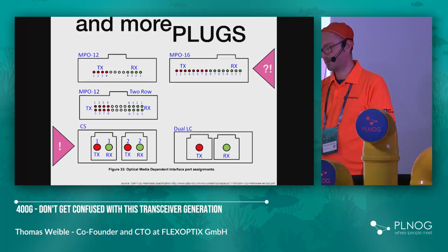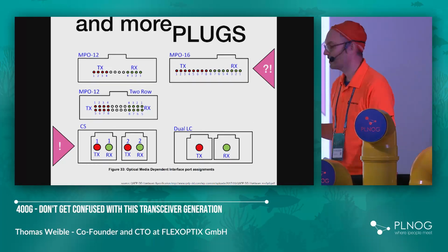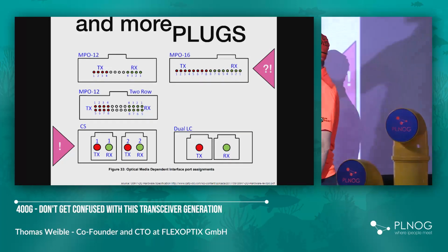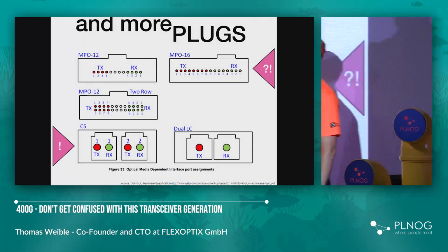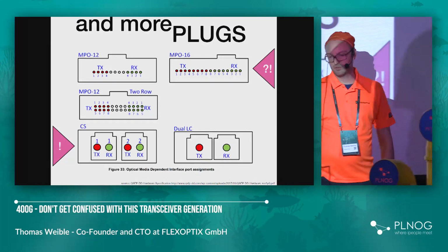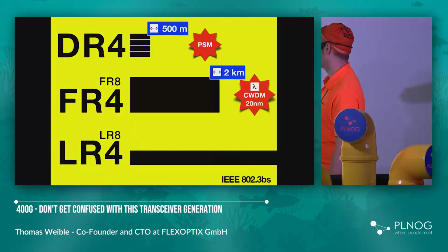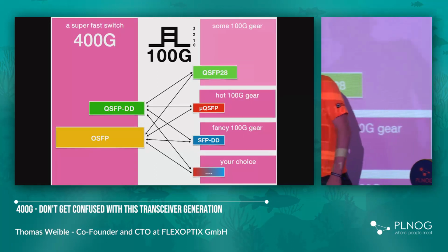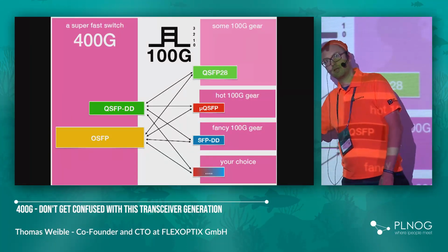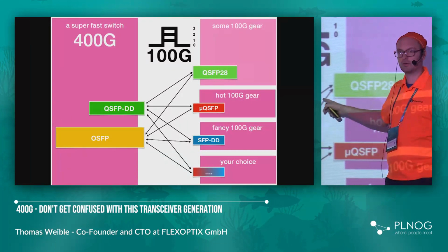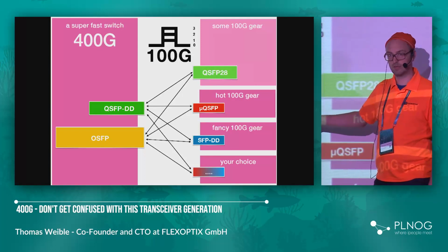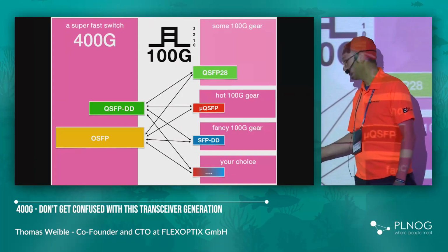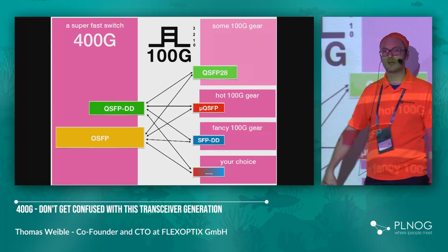I just saw a couple of days ago a new application getting rid of the MPOs, especially about MPO 16 or MPO 12. When it comes to this type of application, I have to go back to that one, because currently you have an MPO plug, you have to plug it in. And if one connection is making trouble or the plug is making trouble, you have to unplug it entirely, so all the other 3 links will drop down.